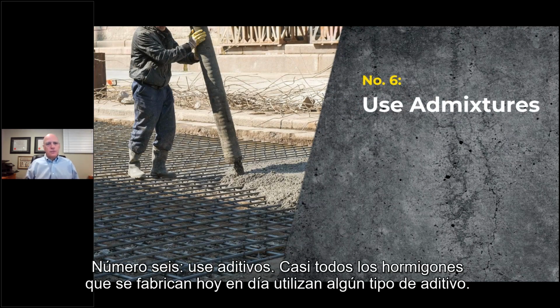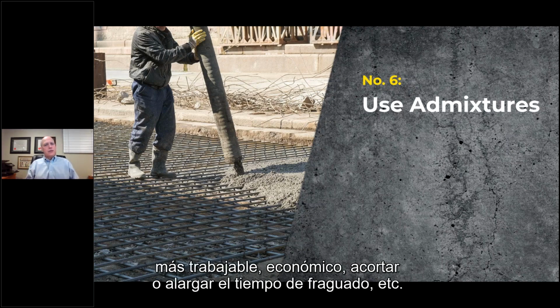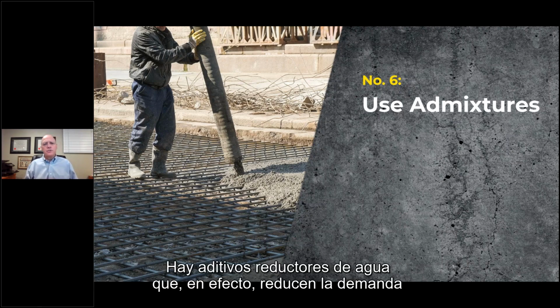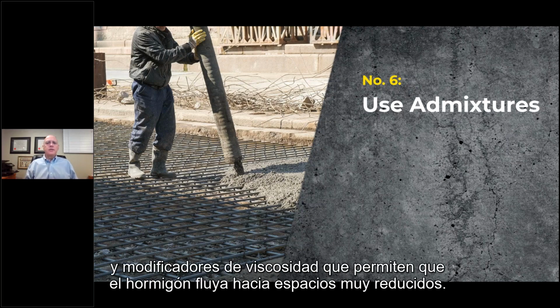Number 6, use admixtures. Nearly every concrete made today uses some sort of admixture. Most affect the plastic properties in order to make concrete more workable, economical, shorten or lengthen set time, and so on. But without admixtures, concrete could not be pumped hundreds of feet in the air or transported hundreds of miles, and many architectural finishes could not be achieved. There are water-reducing admixtures that in effect reduce cement demand, accelerators that improve strength gain, and viscosity modifiers that permit concrete to flow into very tight spaces.